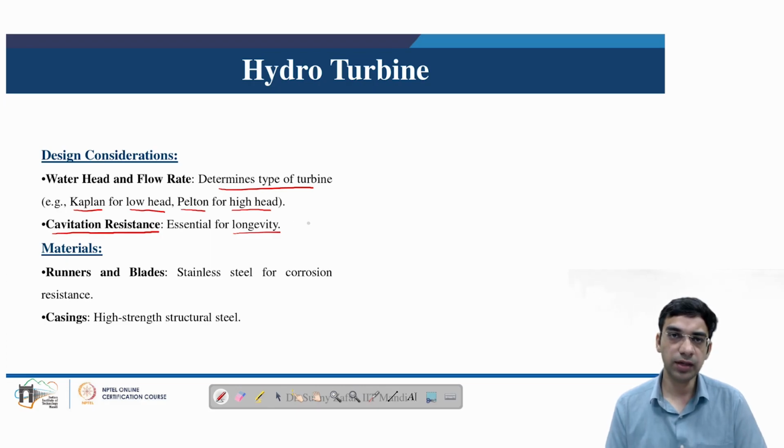These collapsing water vapor bubbles impact the surface of the essential components like the guide vanes and runners of the turbine. So there they create shock waves and there is material loss because of the bursting bubbles of the water vapor, which is known as the cavitation erosion. So hydro turbines have to be importantly designed to manage the cavitation erosion for longevity.